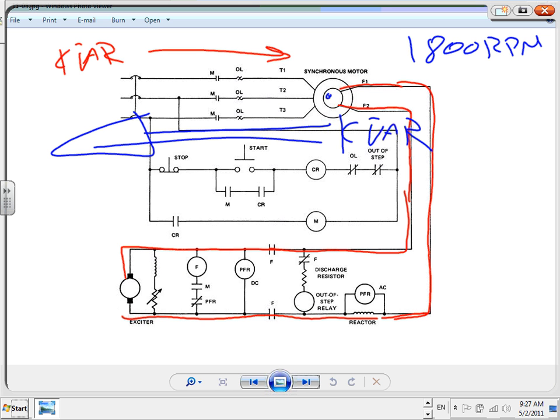I don't know if you remember when Tim was talking about how, to maintain the frequency, we add more DC voltage on the rotor, and to pick up the load, we basically burn more fuel. Anyway, if you add more DC, you're pumping power out.